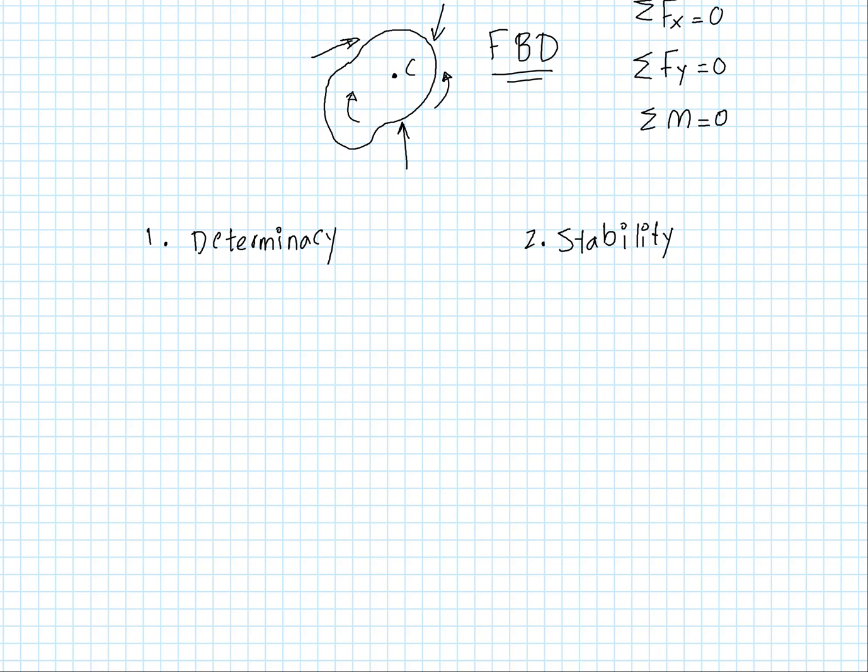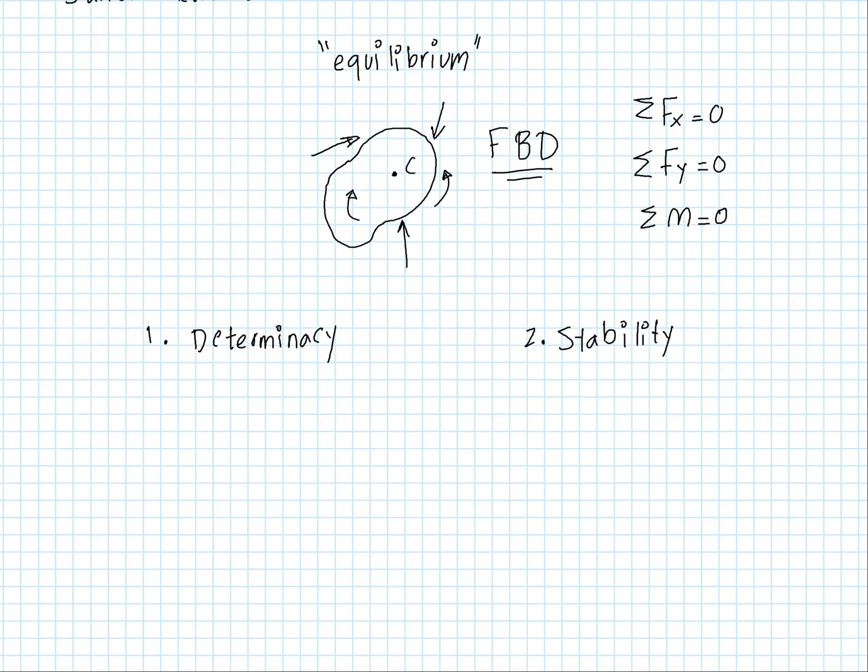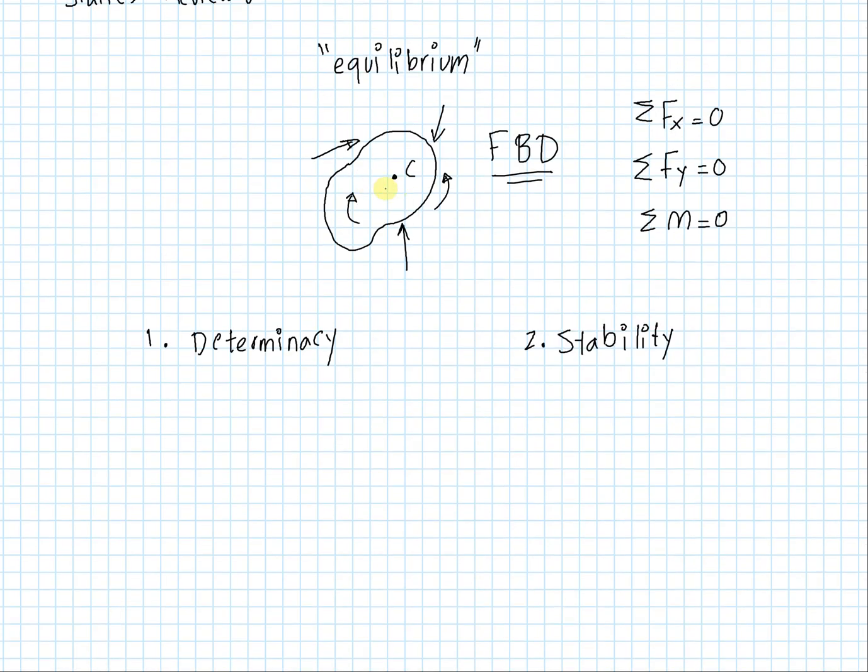There is a very basic definition that states that when the unknown forces inside a structure, so if you're looking at a truss system, when the forces within each truss element can be determined statically from simply the equilibrium equations, and the equilibrium equations are pretty much these equations shown here. We're going to refer to these as the equilibrium equations. Then the structure is statically determinate.